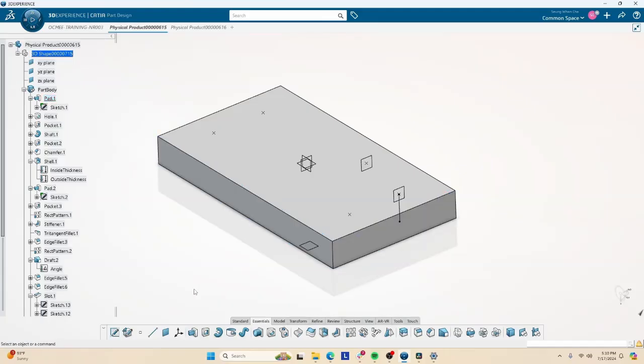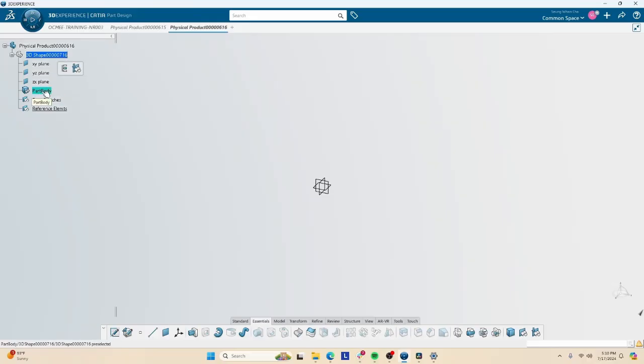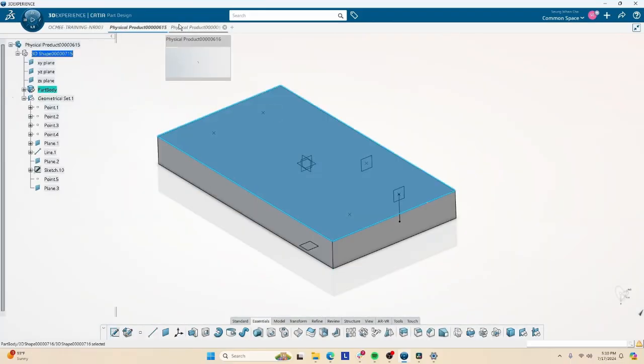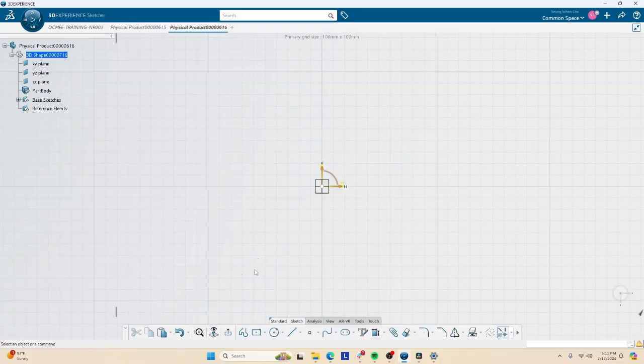So in order to make those links within each other more obvious and more clearly defined, one good way to do it is, one, define your sketches separately to know what your sketches are being linked to, and two, use Boolean operations with multi-body parts in order to more clearly separate out your different features within your 3D part. So one example, connecting to the two pads I was pointing out before, would be, let's say I do a sketch in my base sketches here. Again, there are small nuances where different people do it differently, but here's one example of it.